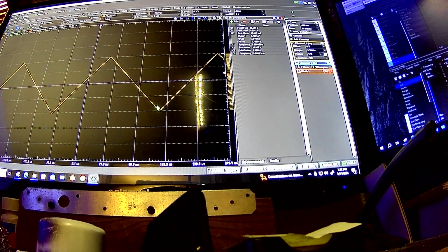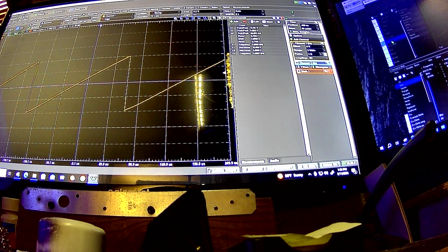This is almost a pretty much perfect straight line. But that's because the slew rate isn't having a big impact here, because the waveform itself is generally pretty gentle, even though it does have these little slew rate driven elements that are so small. Apparently, it's not enough to generate a big distortion, like you were seeing in this here, because that definitely has distortion.